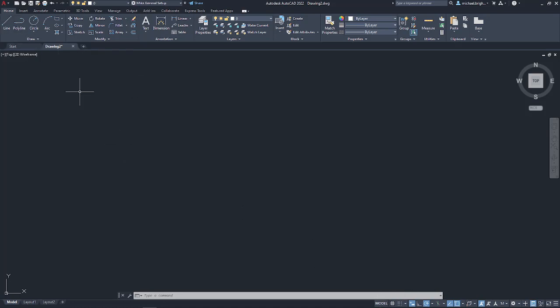So the first thing I'm going to go through is the line. It's very basic again. The line is the most basic and common object in AutoCAD drawings of any discipline. So AutoCAD electrical, AutoCAD, all of them use lines, obviously. Very, very basic. Each segment in an object is a line, and it can be edited separately. You can assign properties such as layer, line type, line weight. The simplest method to draw a line is to click two locations in the drawing area. However, you'll want your drawing to be much more precise.